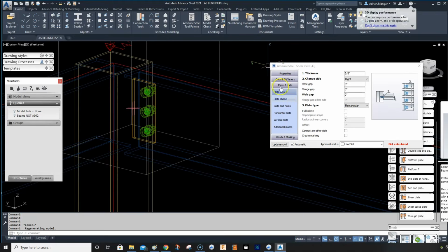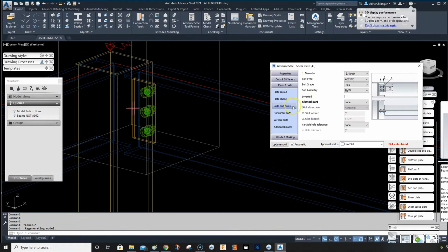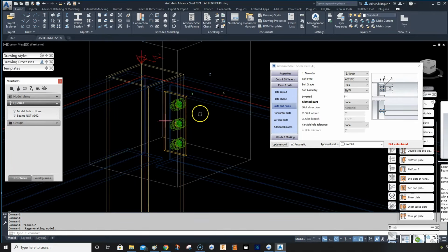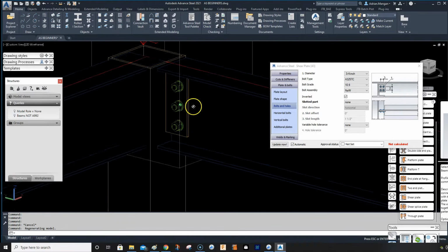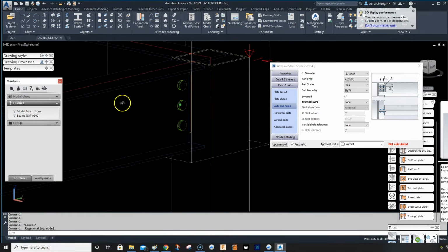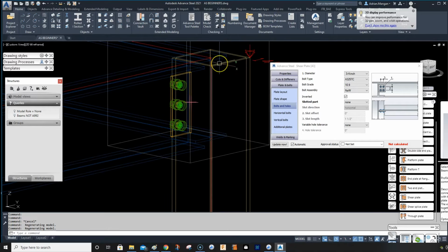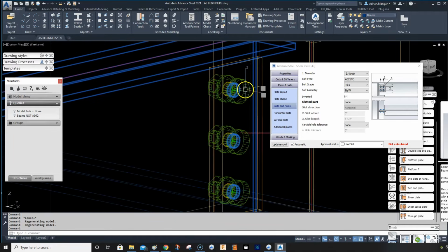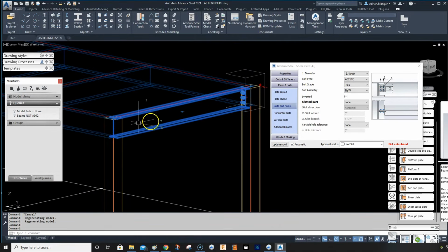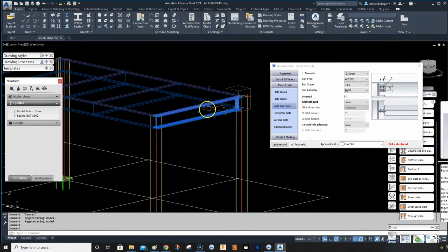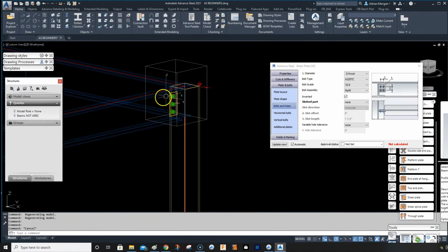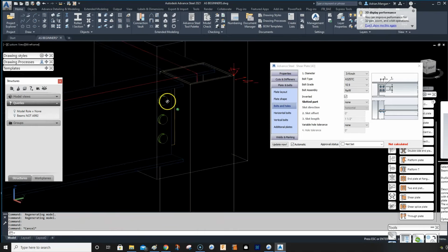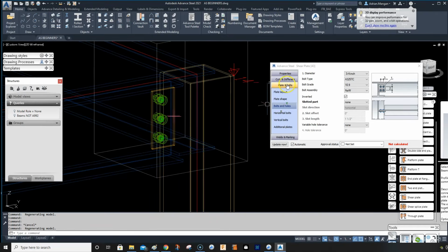So when you switch sides, you also have to go to your bolts and invert your bolts. So there's the bolts inverted, so now the bolts will be associated with the beam. So if you send the columns to the job first, they won't have the bolts. Then the beam will have on its drawing, the bolt list will include these 3 bolts and the 3 on the other side. So that's important. A lot of people don't know that. That is quite important.